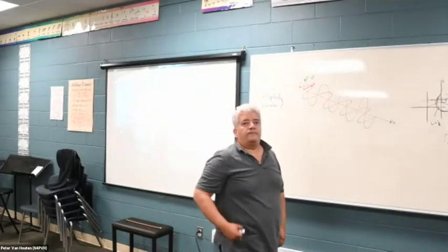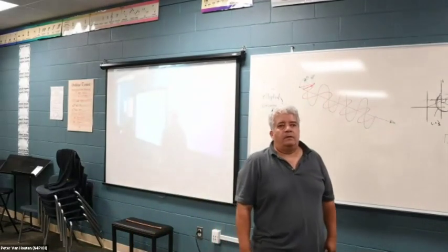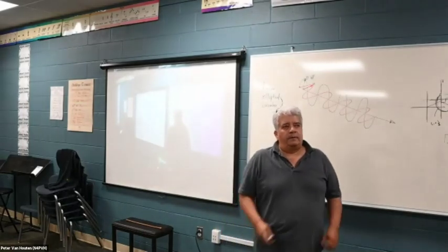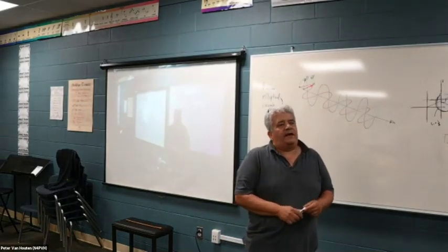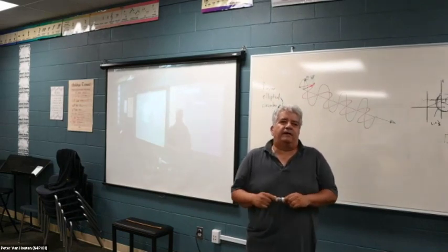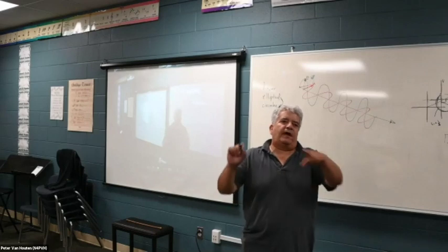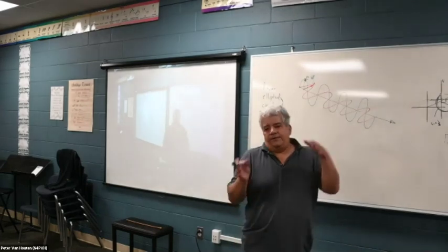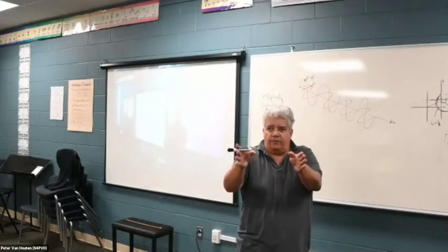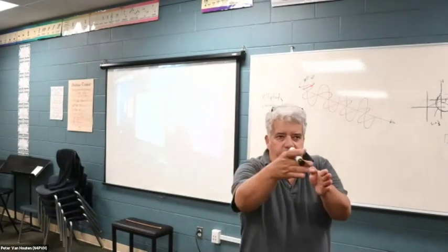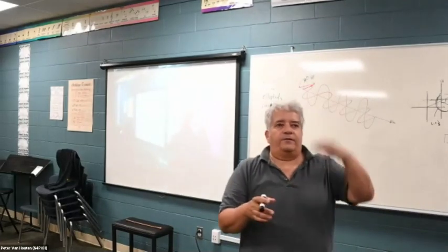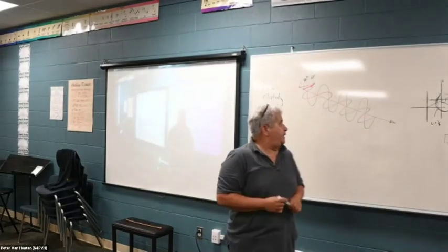Is that also why you get that periodic fading on those signals, because it's rotating and you may have a linear polarization? There could be that effect, but the fading is mostly when you have reflections and then you get multipath from the transmitter to the receiver. You send a signal directly to you, but then a little bit bounces somewhere and then goes back in your direction, and they get to you out of phase. And that may cause the fading.